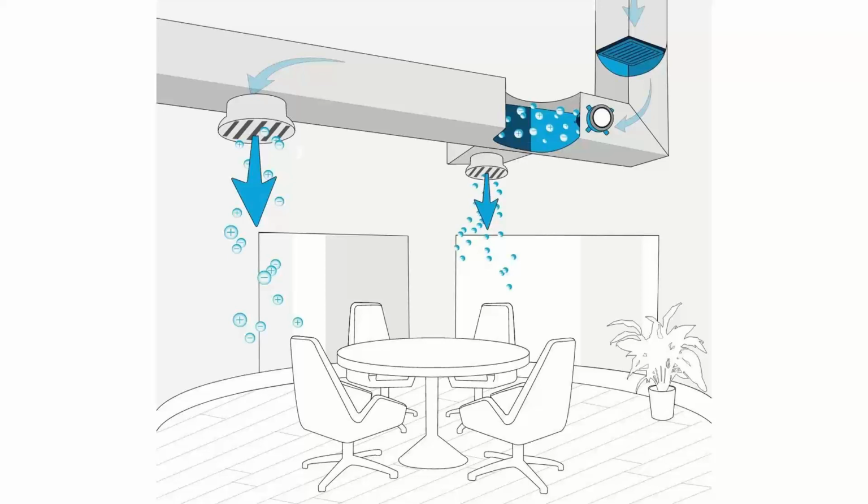So in a really big building, like a multi-story building, you got 10 floors, I may want to put a duct-mounted one on each floor and let it take care of that floor versus putting one back at the air handler. The chance of the ions getting from the penthouse all the way down to the first floor and still having ions left is kind of hard. So I may choose to do some duct-mounted ones instead.